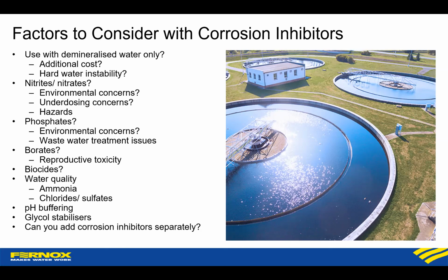Biocides, this is obviously a key one for geothermal systems. Depending on your base antifreeze fluid, which we'll come on to in a second, you may or may not require that. Obviously, it's a low temperature system.